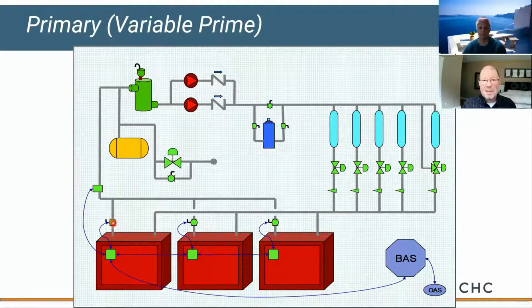Now, the last thing that's really important is your system pumps are being controlled by VFD drives, right? And they're responding to system pressures as your two-way valves are opening and closing. So flow rates and pressures tend to fluctuate. How do you maintain balanced flow through multiple boilers when they're piped primary only? The only way to do it, the only easy way to do it, is what we call reverse return, okay? This is where it's very critical.